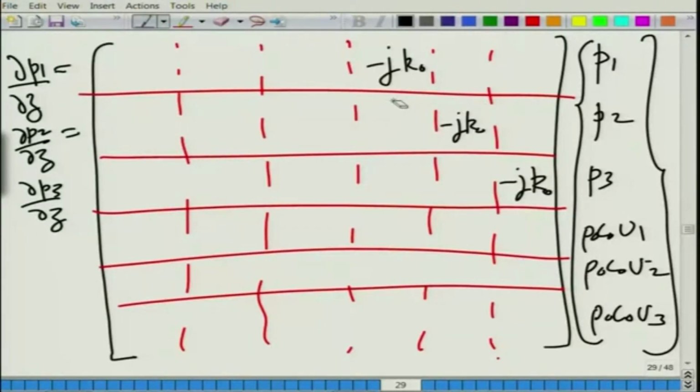Okay. Now comes the continuity equation, which is obviously more challenging, because here it is an exchange, like I have been mentioning at the very beginning of the lecture on the perforated mufflers. It is basically the exchange of mass through the perforates, and that is why the continuity equation has to be modified. Okay. So, we get this.